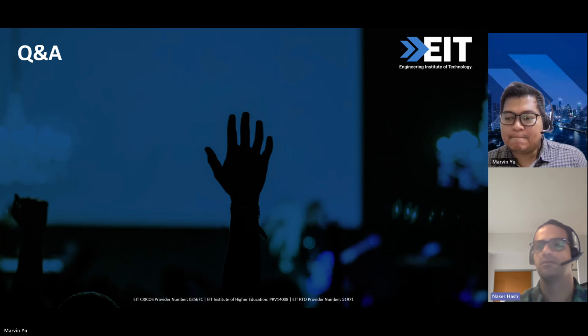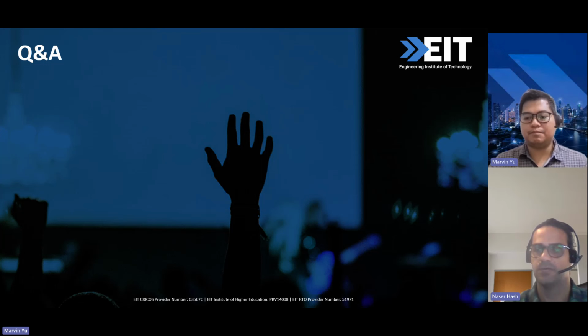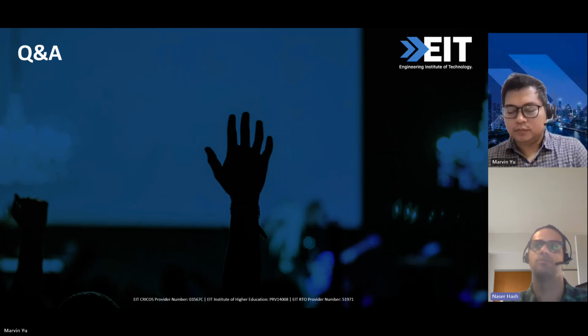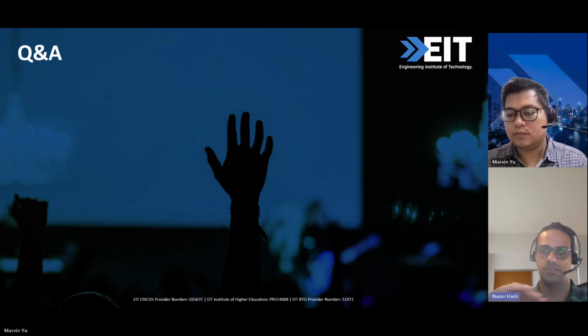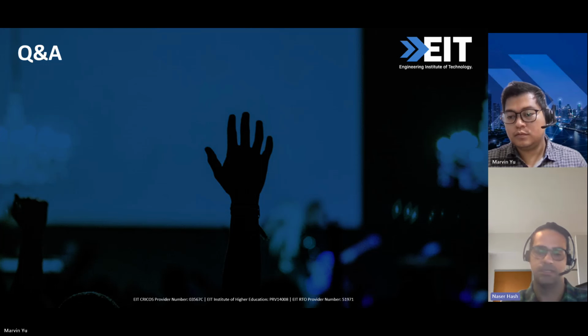So that's a good question. Definitely the history of the data is required, because we need to understand how the equipment has run over the last two years, or one year, and what the condition of the equipment is at this stage. The solution, which is a Markov chain, as I said, looks at the trend of the data and then predicts the future trend. So if you have at least six months of high-frequency data, the trending can be easier.